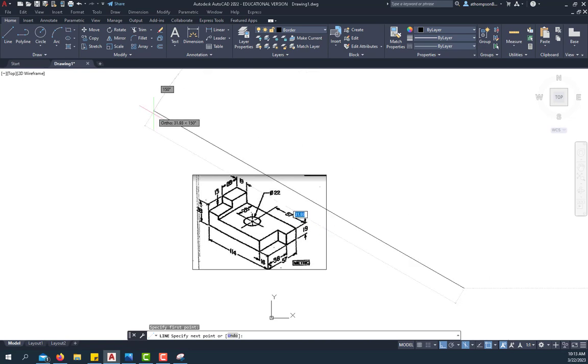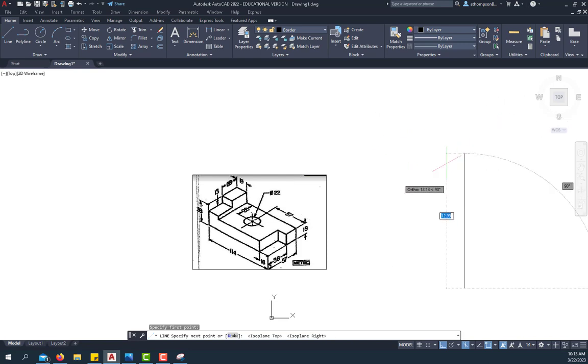But as long as you're in a plane that will go back at this angle to the left, you can hit F5 and kind of see your options. If I hit F5 and now I'm in iso top, I can still do a width dimension. But if I hit it again, I cannot go back in that direction.